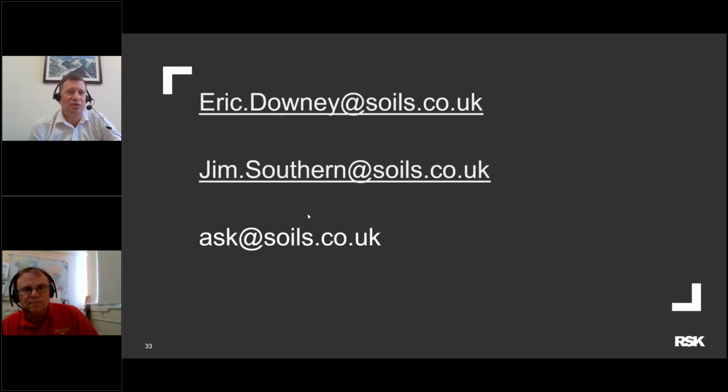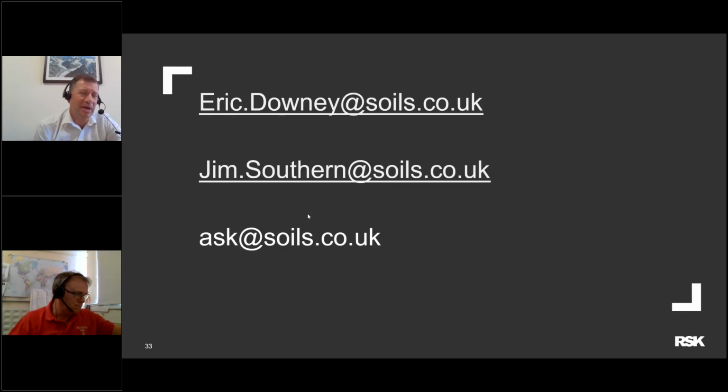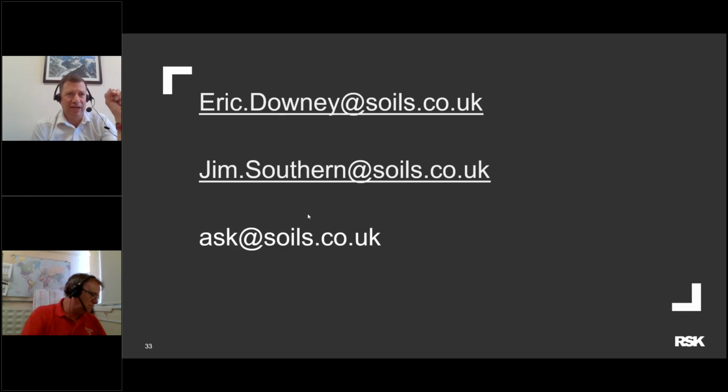No, it is. It all depends on the ground conditions, the amount of testing that we need to do. If we've been able to reduce down, so let's say the client is looking to get 60 meters, we then do need to start maybe in 8-inch or 12-inch casing, reduce down to 10-inch, 8-inch, 6-inch, and then, so it is a big process.